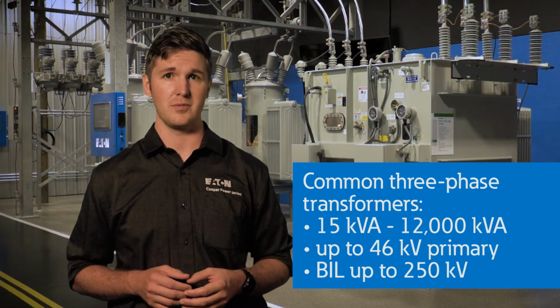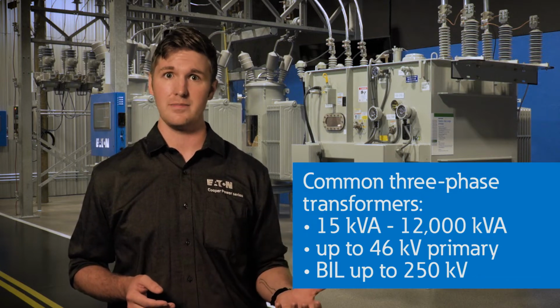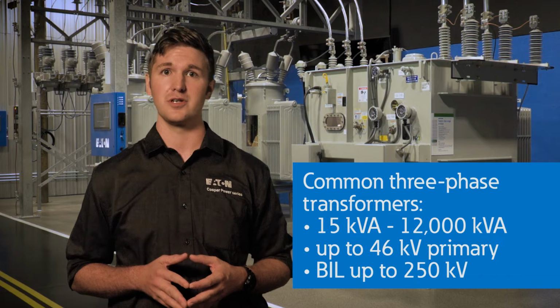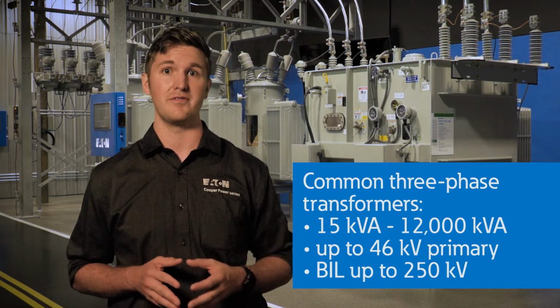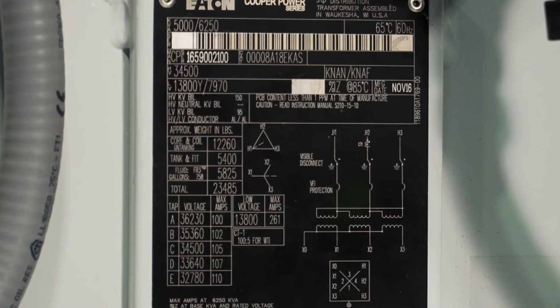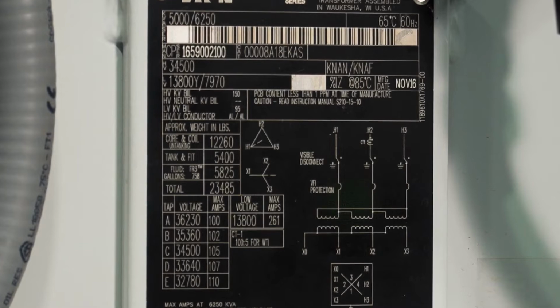Common three-phase transformers have a kVA ranging from 15 all the way up to 12,000 kVA, with primary voltages going up to 46 kV and basic insulation levels, or BIL, to 250 kV. Medium voltage distribution transformers are engineered to order and are often based on customer specification.